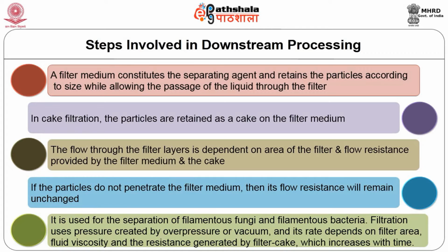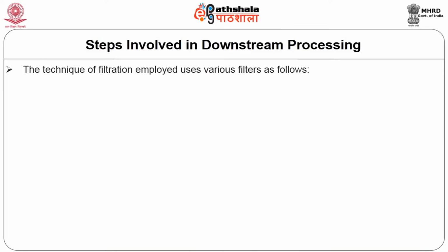Filtration uses pressure created by overpressure or vacuum, and its rate depends on filter area, fluid viscosity and the resistance generated by filter cake, which increases with time. The technique of filtration employed uses various filters as follows: batch filters, continuous filters and cross-flow filtration.